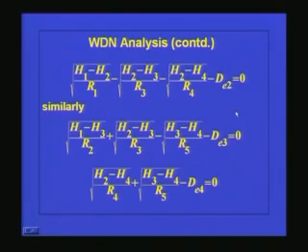I will assume what is H2 and what is H3 and try to get what is H4 here, and I will substitute what is H4 here and the assumed value of H3 here and get a better value of H2, and I can keep doing this trial and error procedure or an iterative procedure. Once I do this, eventually as the iterations proceed, I may have stable values of H2, H3 and H4, and I say that the system has converged. This is an iterative, what we call numerical method.